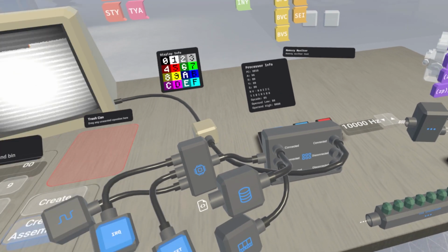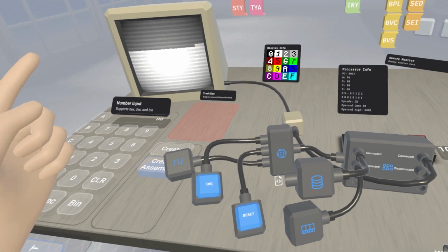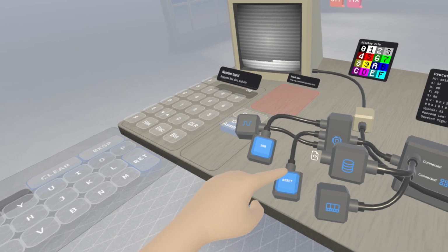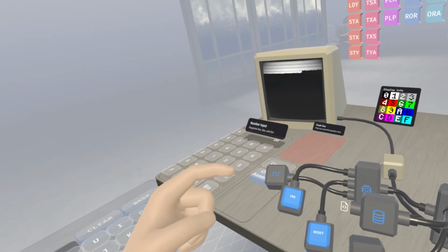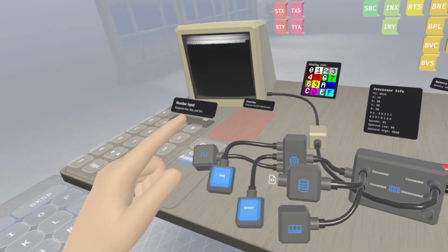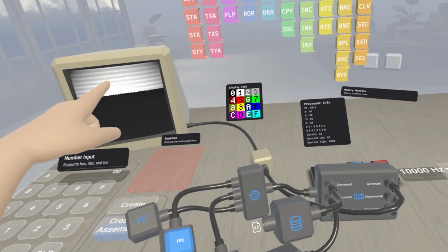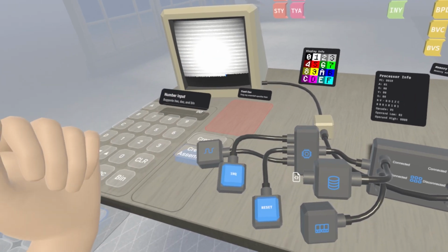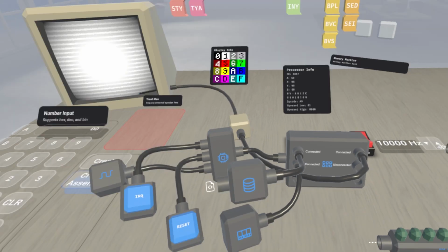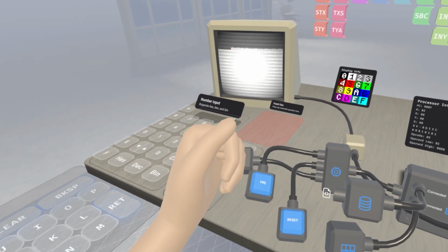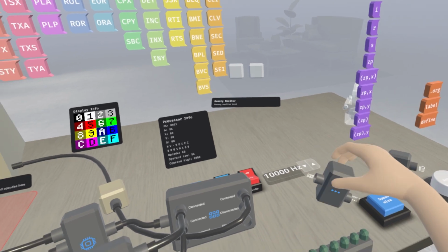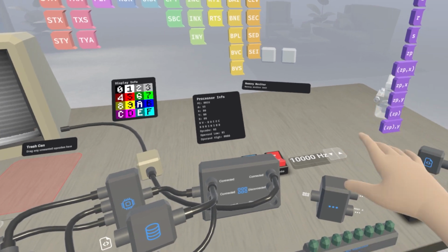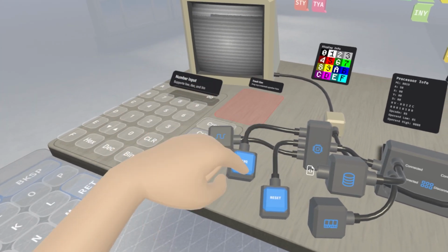This is a great way to show people how the computer can be put together and what all of the main pieces of it are. And just to demo some stuff here, if I press the reset button, it resets to the beginning of the program each time. The memory bus is telling any device attached to it to reset as well. And that does include stuff like the RAM, for example, at this point, and also obviously the monitor. When we connect to the versatile interface adapter in a little bit, that will also be something that can be reset so that our ports get reset whenever we hit that reset button.